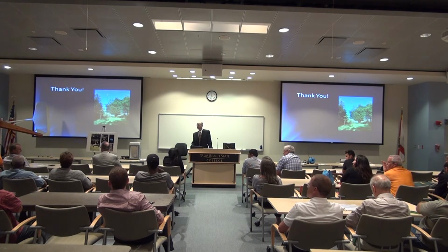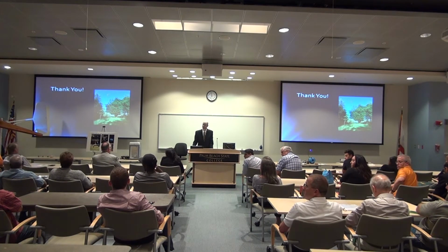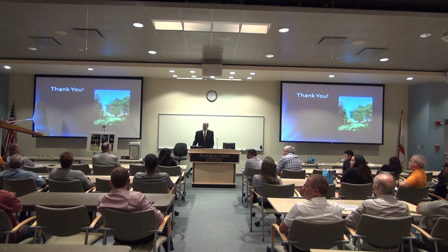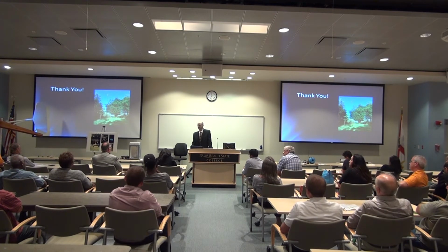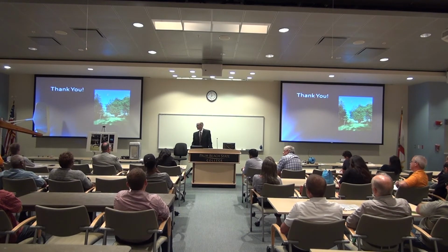Yes, sir. Maintenance, if you did need that put up in the air and functional, how long do you think it would be until it requires some maintenance? So a wind turbine like this would turn about the equivalent of what a car would do for about 200,000 miles every year as far as the number of rotations. So annually, it should come down, half the blades re-oiled, half the bearings repacked, and